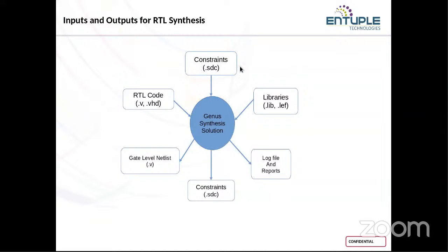The other input file is your SDC. .sdc represents your Synopsys design constraints, where you will be specifying your clock information, along with the input and output delay information of your design. If you are working with combinational logic, your SDC file is optional. If you are working with sequential logic, your SDC file is mandatory, because your sequential blocks play a major role on the clock signal itself. Depending upon the clock signal, it will be defining your logic. So at that point your SDC file is mandatory, where it will have your clock information, along with your input and output delay information. So SDC refers to Synopsys design constraints.